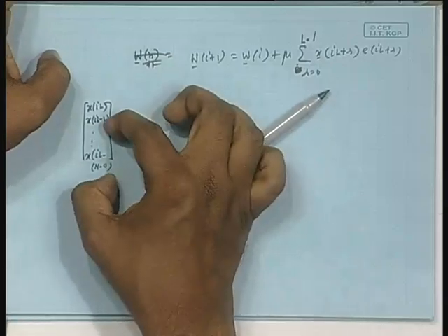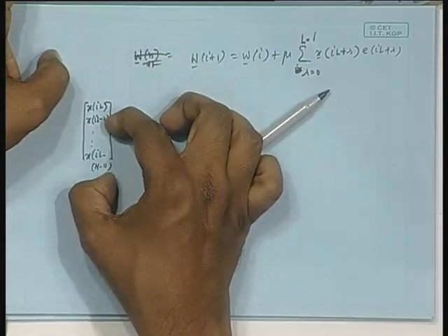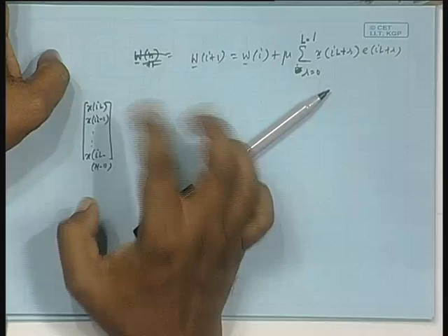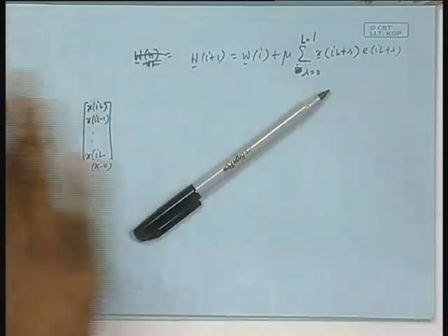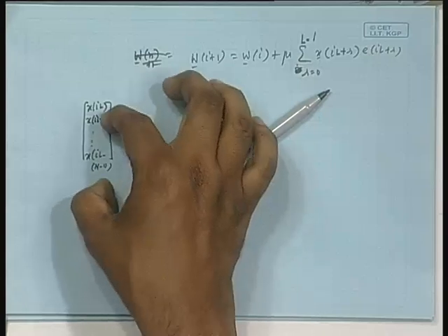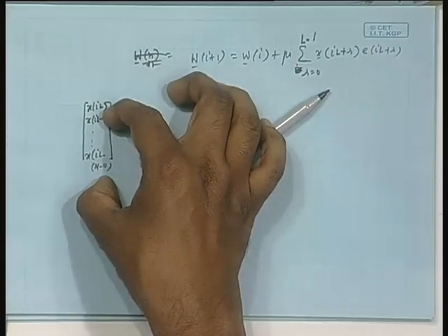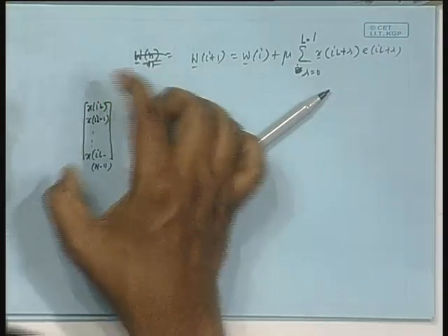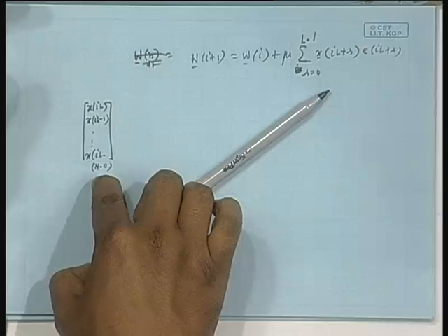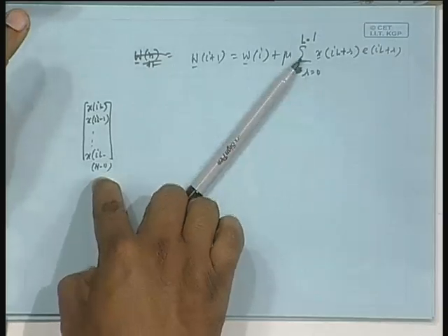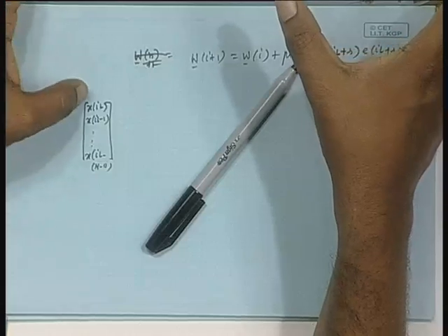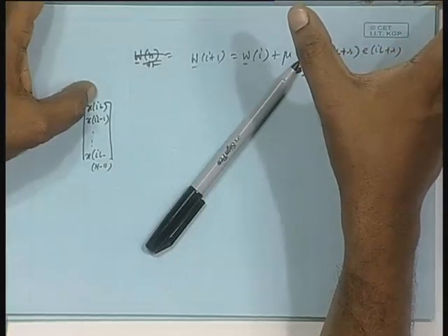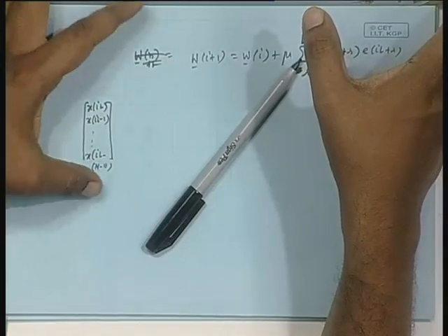So, this is that overlap zone. I will take the last n minus, not m anymore, filter length is not m here, it is capital N, I have just changed it. So, the last n minus 1 data from the previous block correspond to that. In my modified scheme, they have got appended with the current data block. The current data block earlier was starting here, but I have appended this part.